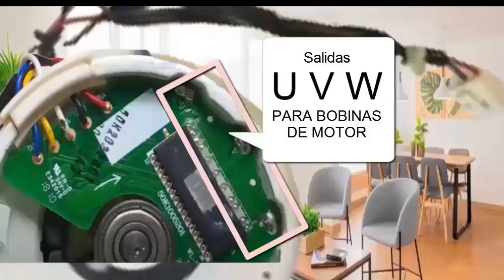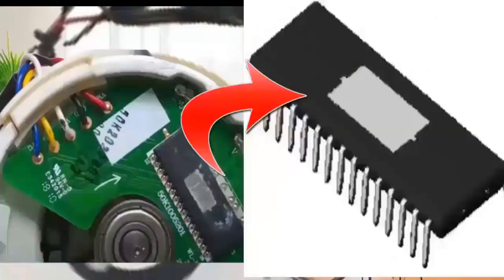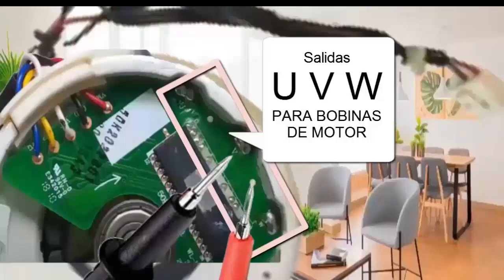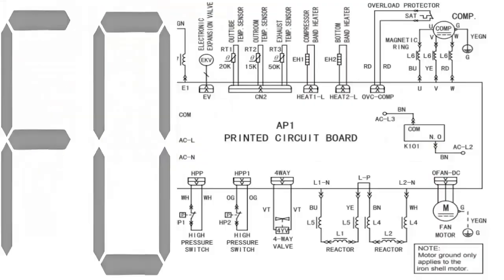7. When problems are detected on the internal BLDC motor's electronic board, focus on the board's IPM controller, which can be replaced with one of the same reference. If no electronic issues are found, disconnect the electronic board from the coils and measure the electrical resistance of the 3 coils. All measurements should be equal.